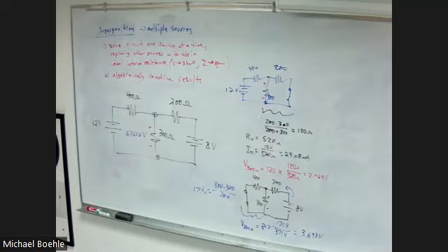All right. So when it comes to Thevenin and Norton, what are we doing? Well, we are basically trying to find an equivalent circuit around a component. So in this example, since the component I want to learn about is that 300 ohm resistor, that's the one I'm going to Thevenize around.